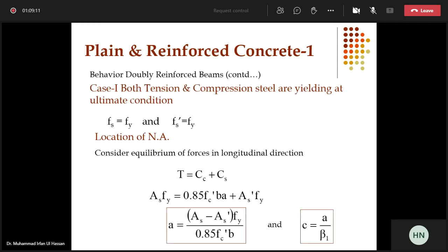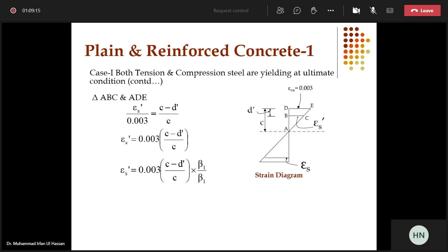So that's why the doubly reinforced beam is normally not common. But if it is to be provided, of course, in the house design, and when the architect restricts the depth, then you have to go for the doubly reinforced beam. But that is not an issue, because you can design it and the procedures are available. You can go for the reinforcement on both the sides.